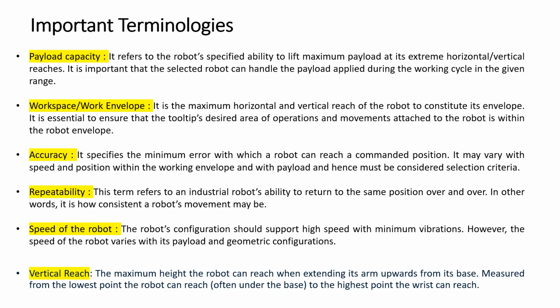So let's say in 1 hour you are doing this 20 times, so in each cycle, for all 20 times, it should reach the exact y position or within that tolerance. So that is nothing but the repeatability.